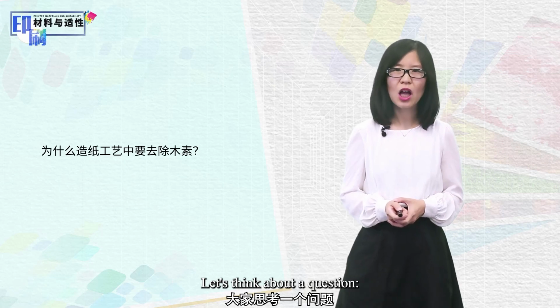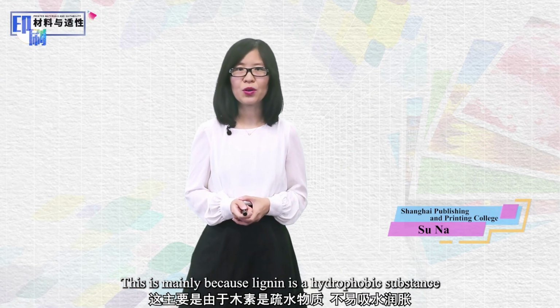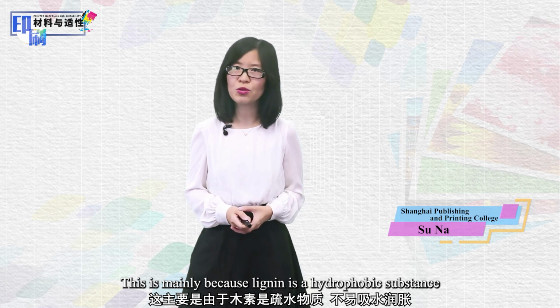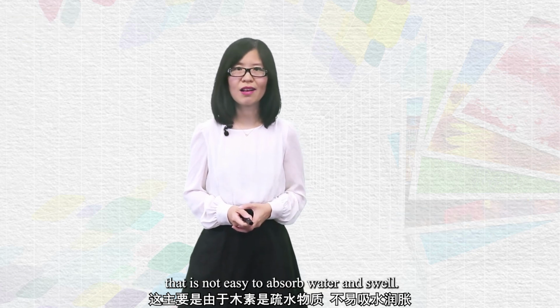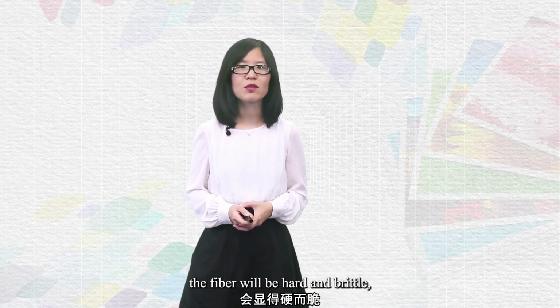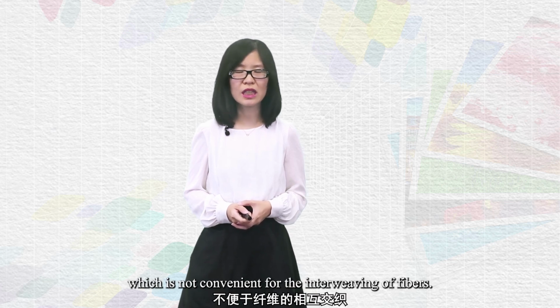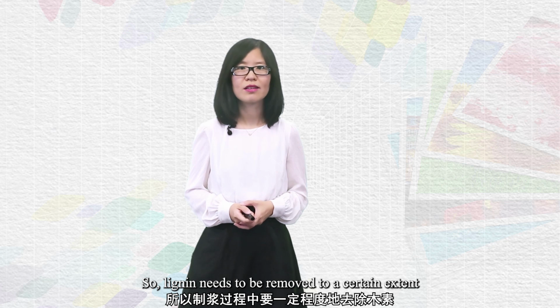Let's think about a question. Why is lignin removed in the papermaking process? This is mainly because lignin is a hydrophobic substance that is not easy to absorb water and swell. Therefore, when the lignin content in the fiber is high, the fiber will be hard and brittle, which is not convenient for the interweaving of fibers. So, lignin needs to be removed to a certain extent during the pulping process.